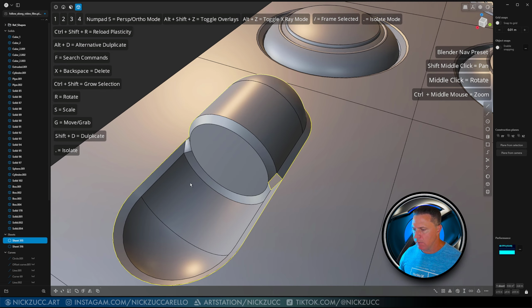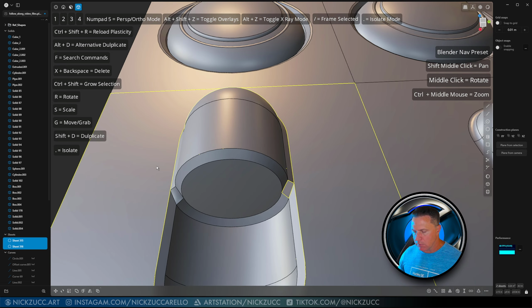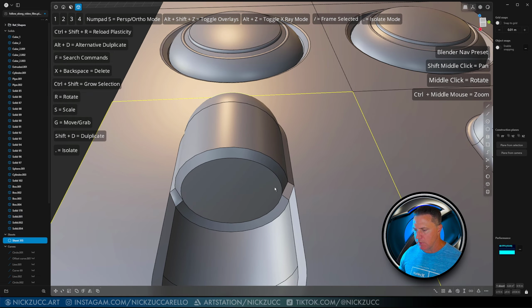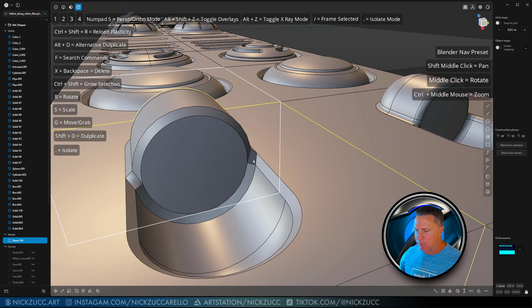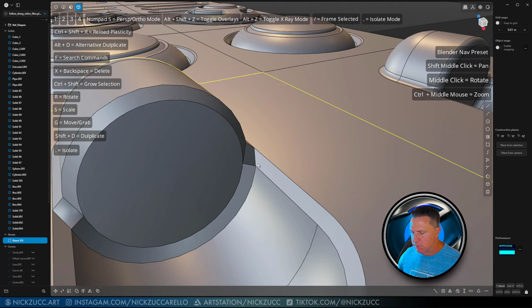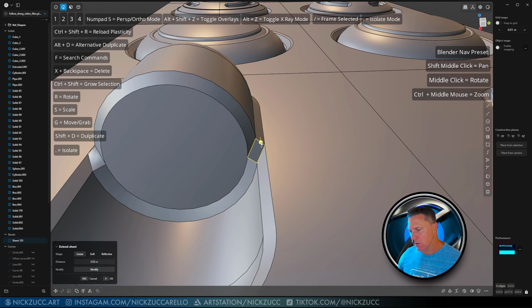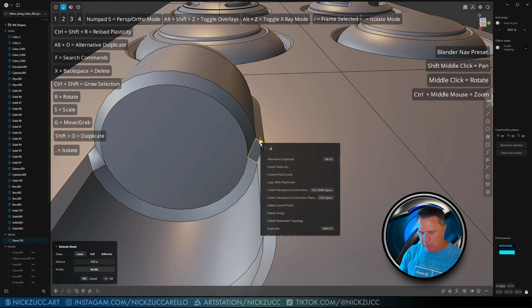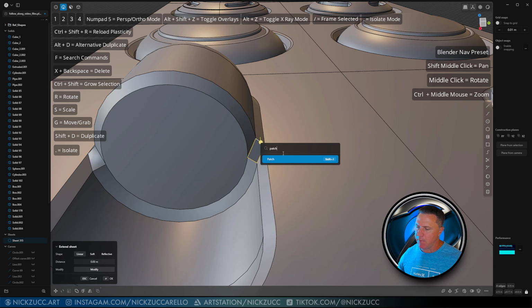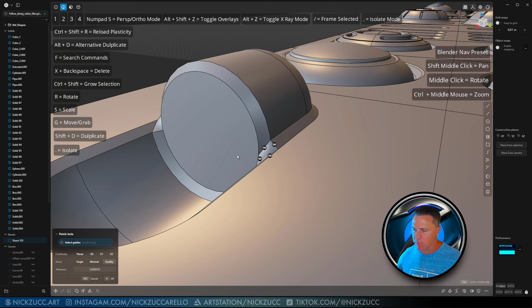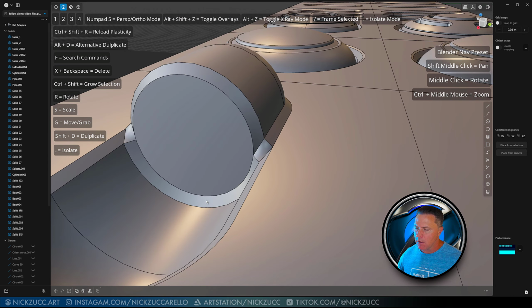Let's tap J there. And looks like we got this here. Tap J. And then the only thing that we've got left now is there's this hole in here. So because I built a hole, I can select these edges, tap F, and type in patch. And I'll go ahead and patch this right here like this, all with G0, and hit OK.